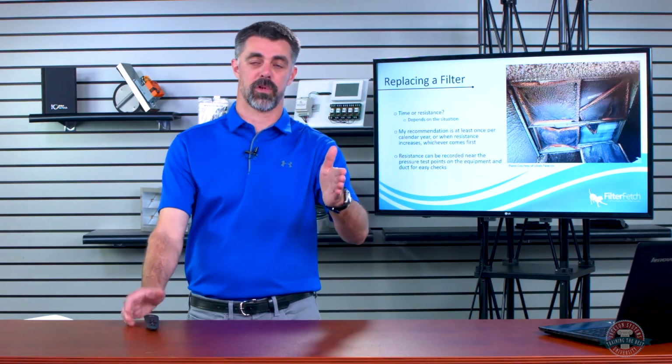That's what they desire. And typically in the HEPA filters, they're going to have 2 to 3 filters in there, and some of them need to be replaced annually at minimum, and some of them need to be replaced every 2 years. So they'll have a primary and a secondary filter in there. They'll catch most of the dirt on the primary, and then the secondary filter typically lasts longer.